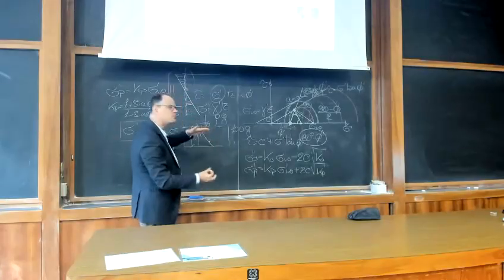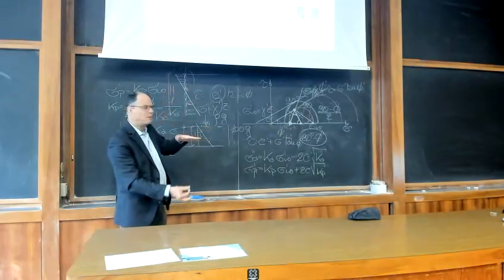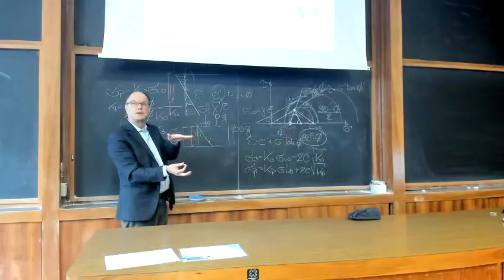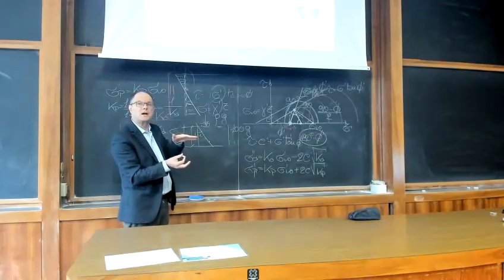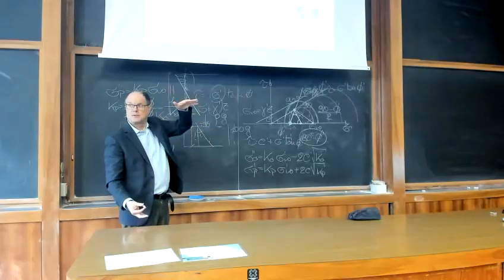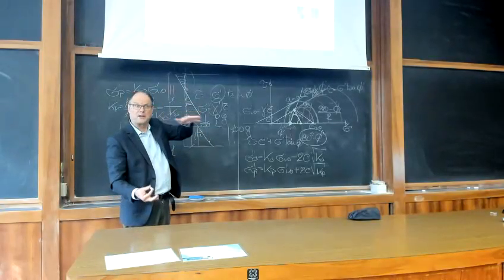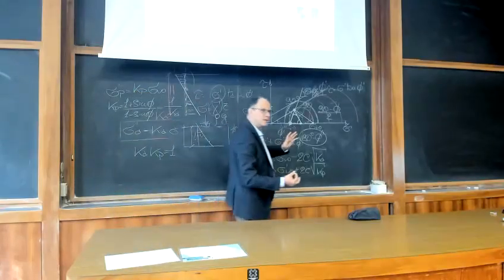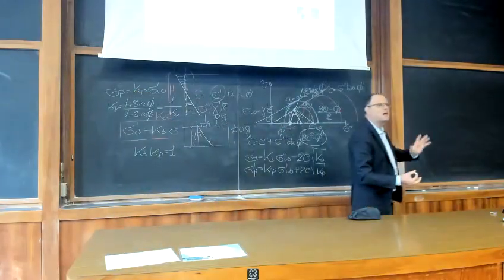So I don't need really to go to that depth. Probably 20 meters is enough. So 20 centimeters of sample is enough to simulate a 20 meter thickness. So you see, the centrifuge is great. It's quite complicated.